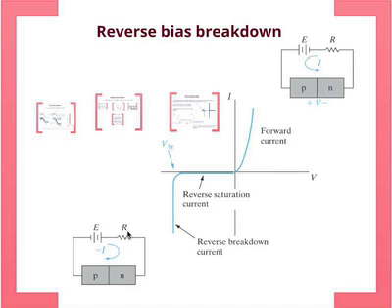So think about it this way: you have a battery, a resistor, and you have something here which is the PN junction, a diode essentially. This has a drop of V breakdown. The maximum current here is basically E minus VBR over R. So by choosing R high enough, you can make the I small, so you don't damage the diode.